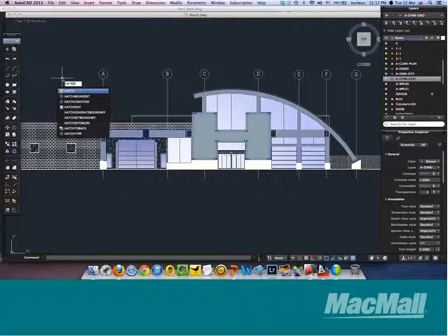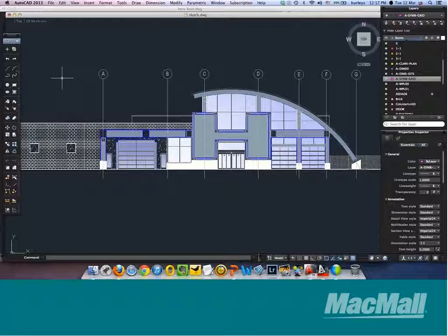But what I want to do is I've got some hatches that are actually not being displayed. I want to send all the hatches to the back, so maybe text and line work are better displayed. You see the garage doors and everything were actually line work, and they were behind the hatches, and I did the hatch to back, and all of a sudden I could see the line work behind it. There's also text, so bring text to front. Let's go and look at some other things here.